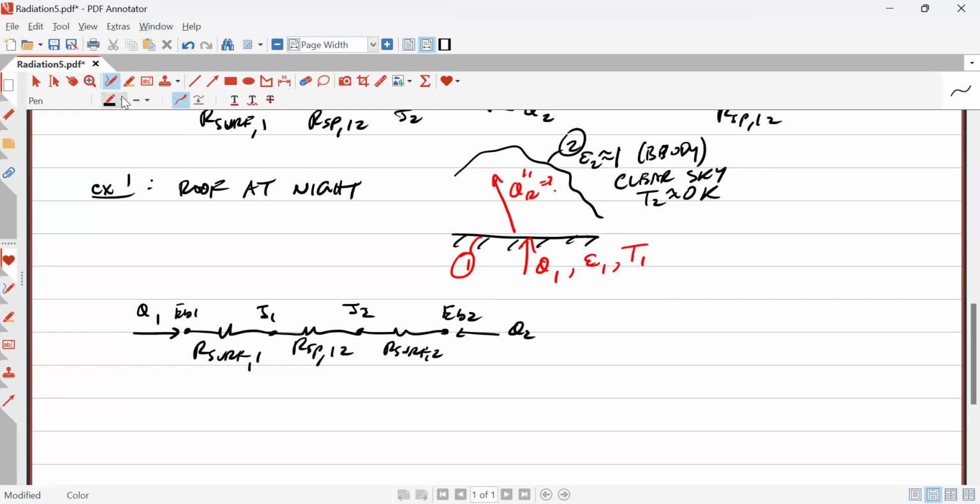All right, well, let's simplify this out. So the idea here first is that since you have Q1 coming in on the left and Q2 on the right, the energy all has to balance out. I didn't mention this, but this is all steady state. So as a result, Q2 must equal minus Q1. In other words, we have a Q1 coming into the resistor network on the left. There has to be a Q1 leaving on the right. So we have Q2 equals minus Q1.